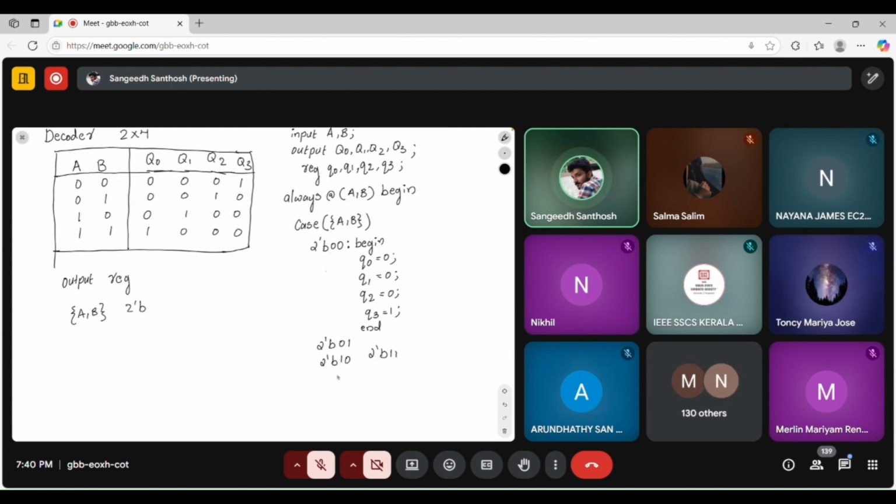Then for case statement, usually we will write one default statement also at the end. Let's say we have 50 or 60 variables inside this concatenation, and we are forgetting to write one condition, and we are testing it in the test bench. At that time, this module doesn't know the functionality of that particular condition.